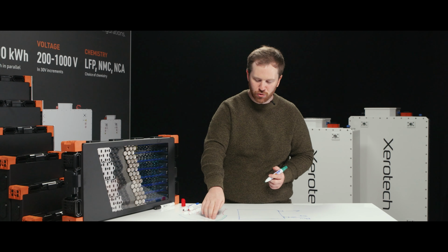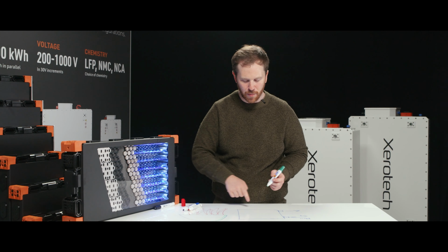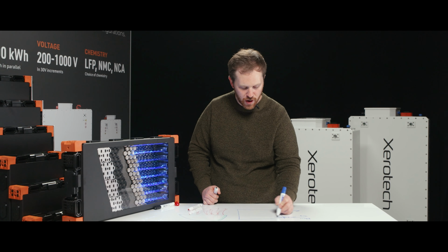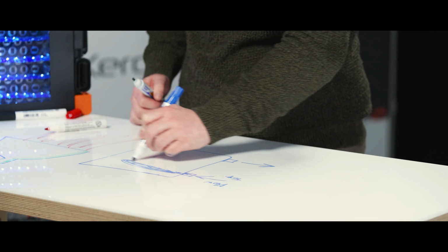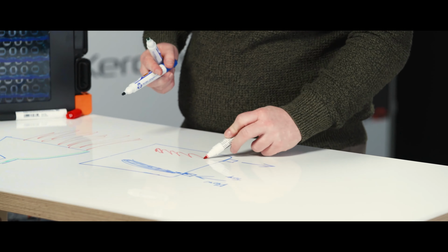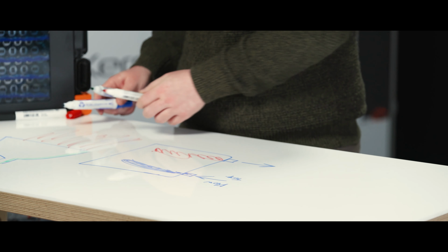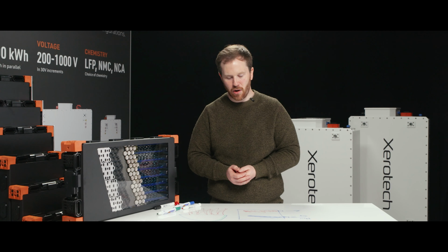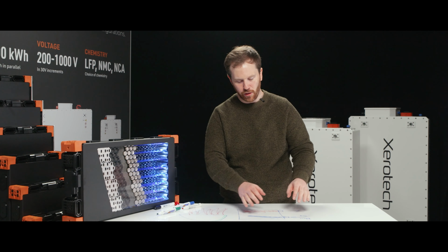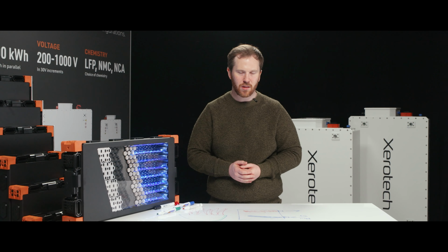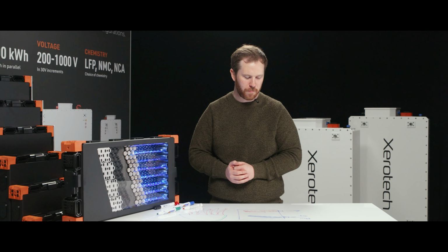So if we had an extremely high heat transfer coefficient in our pack, what that would mean is if we sent in cold water here, this half of the pack is going to be freezing cold, and this half of the pack is going to be much hotter. So it's a balance. And this is when we're getting into real engineering. Everything is a trade-off in engineering. You have to find your design goals and optimize for the best things here. So every real battery system is usually a trade-off on many different factors.